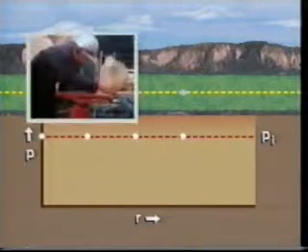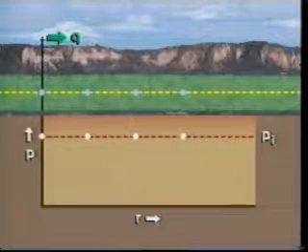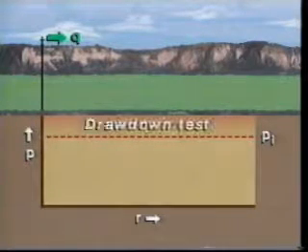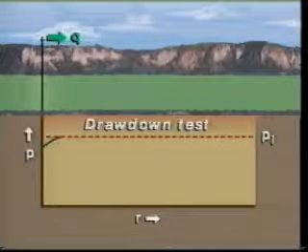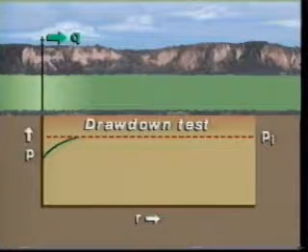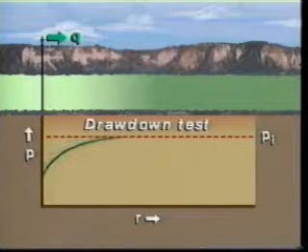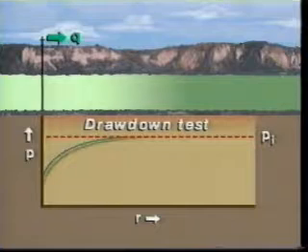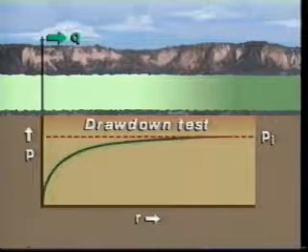Okay, now let's open the wellhead valve and allow the well to produce at a constant flow rate. This type of test is referred to as a drawdown test. Fluids begin to flow into the well, and a pressure transient moves outward, initially quite fast. But as the transient moves further out and more reservoir volume is contacted, the rate of movement becomes progressively slower.